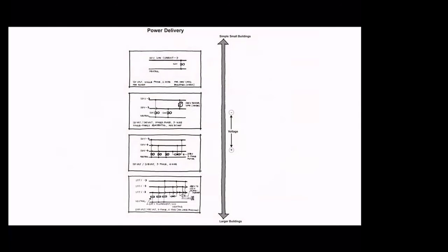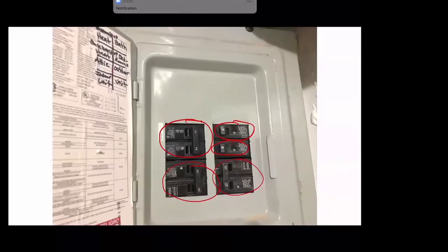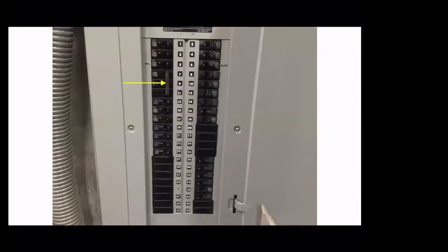And before we go on, let me ask you another question. Go ahead and you're going to actually answer this to yourself. You have to commit to that. So this guy right here, how many phases is that? How many phases is that? Go ahead and answer to yourself. Answer aloud. Make sure you actually commit to it. If you said two phase, you're wrong. It's single phase. So there's only a certain amount of availability for power because we need to standardize all the equipment and electronics that we're plugging in and all the lighting that we're wiring up. And so it's either going to be 120, 240 volt, which is what this is. And if it is, it's single phase. So whereas the three gang together were three phase, the two gang together are single phase. A bit of a trick there.